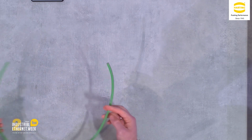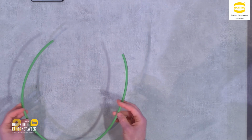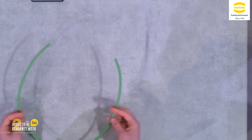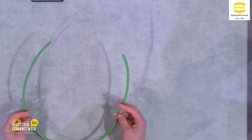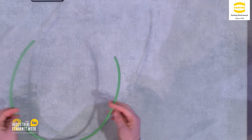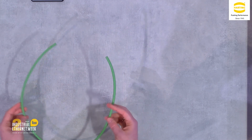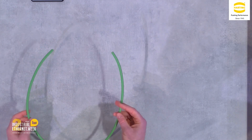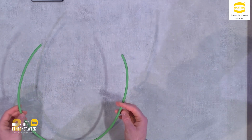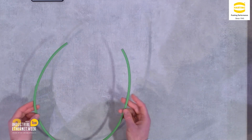So that's a robust but highly flexible design where 19-wire stranded conductors allow use in, let's say, normal industrial applications with high mechanical stress from torsion or repeated bending. We have PVC and PUR cable jackets available, which are flame retardant and halogen-free.